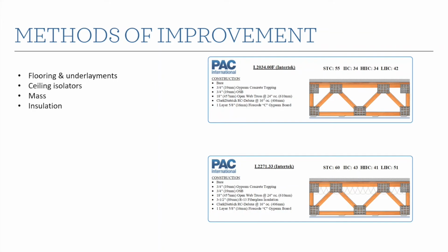So we've created this reverberant space where the sound can just keep bouncing around and build up in there. And when we add the insulation into that cavity, it's the same thing as adding soft surfaces, acoustical absorbers, into that restaurant space, right? It quiets it down because it absorbs that sound that's bouncing around. It's the same thing that goes on in these assemblies. So the insulation is not blocking the transmission of sound. That's another common misunderstanding. It's just absorbing, reducing the sound that's bouncing around inside this space.